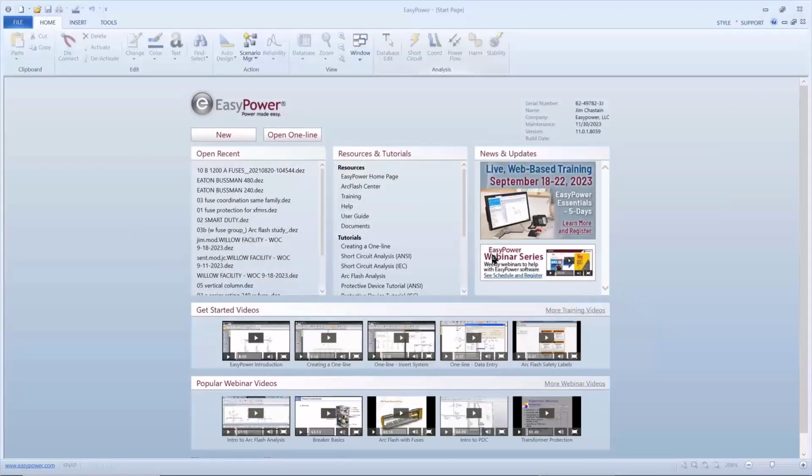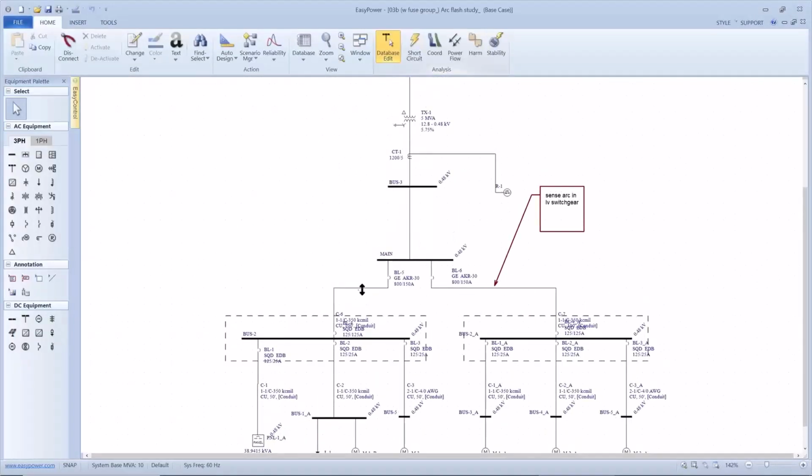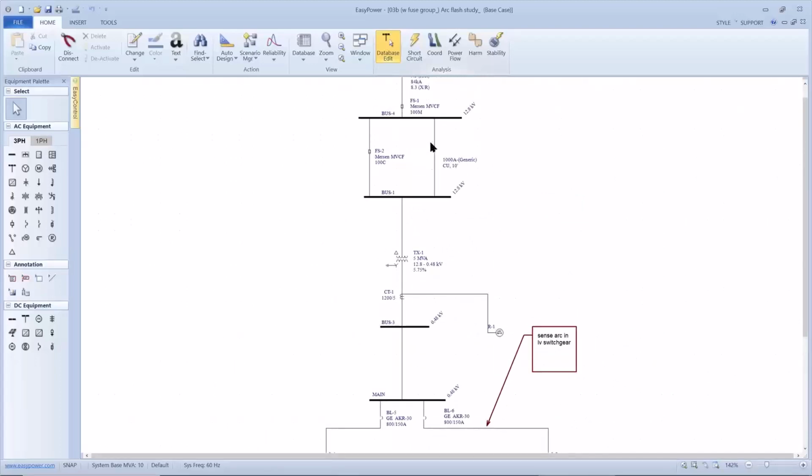It's simulated very similar to arc flash, where we have a relay that's tied to the arc sensing element, say a 751 or similar relay, that can sense the triggering device for these fuses. And normally the high current would go through the main fuse and my low impedance link. And if I sensed an arc, it would open this switch and force the current to go through my current limiting fuse and thereby give me protection downstream.